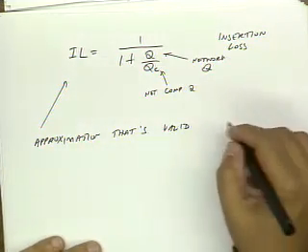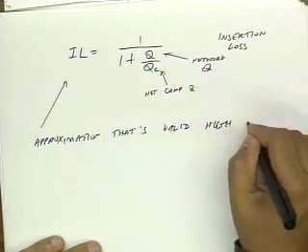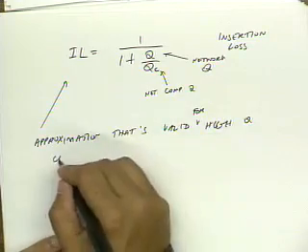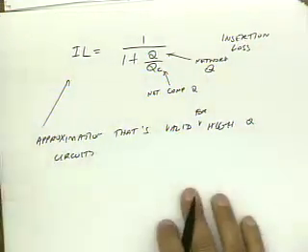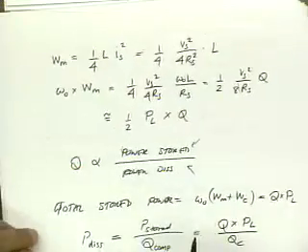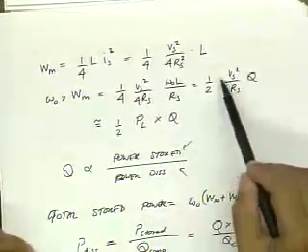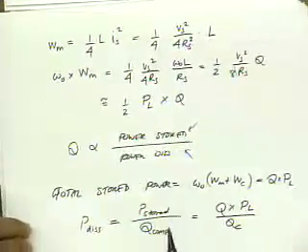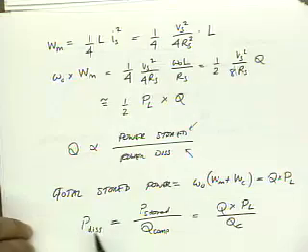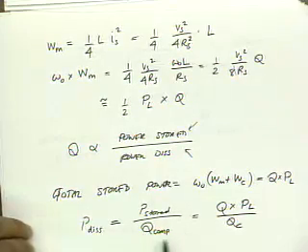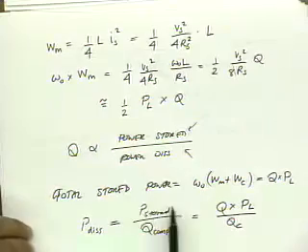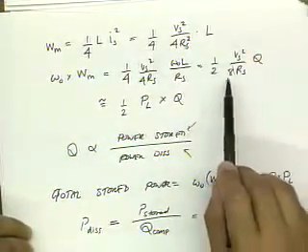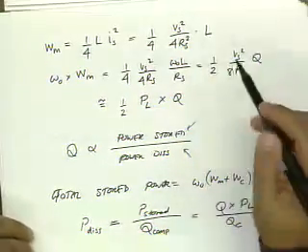And it's more and more valid as we go to a high Q circuit. The reason it's an assumption is I made a lot of assumptions here. The biggest assumption at this point is assuming that the power dissipated is simply the power stored divided by the component Q. Even though this is exact, I don't really know the power that's stored that accurately. I made an assumption here that this is roughly the power that's stored,